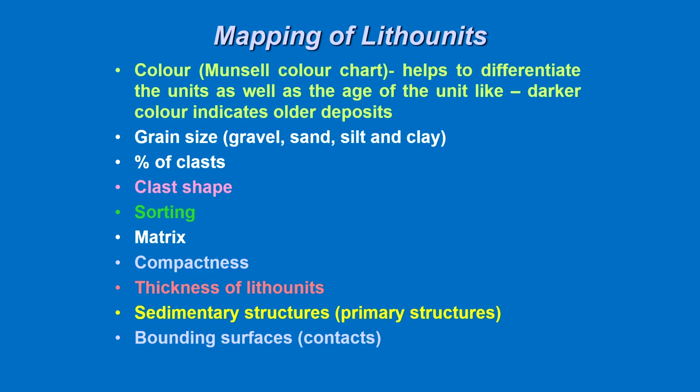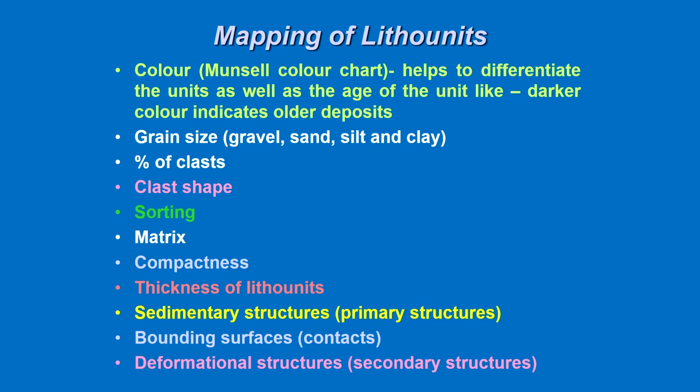so based on this understanding, we usually prepare our trench logs. Okay, what I have shown you in the previous lecture, that how we demarcate each and then put it on the graph sheet. And then finally you have to look for the deformational structures, and this will be done based on your shear fabric or deformational fabric of the material you see in the exposed trench. So very carefully you can do that.